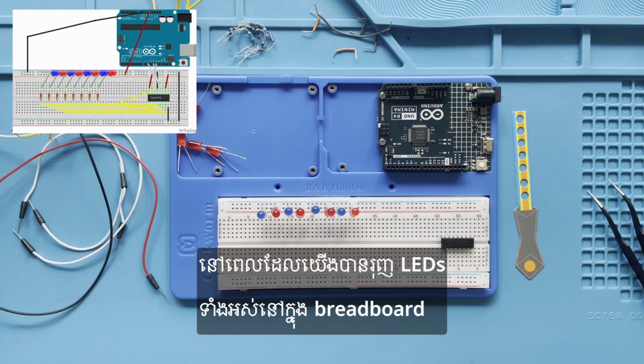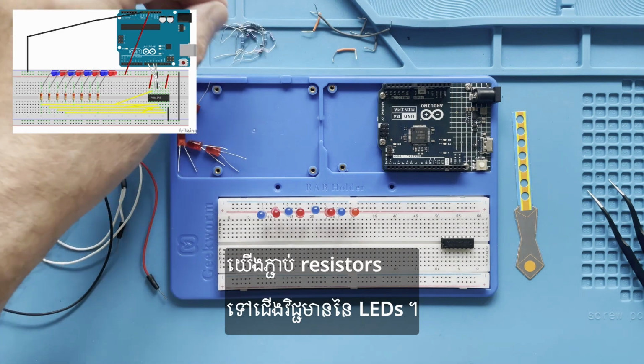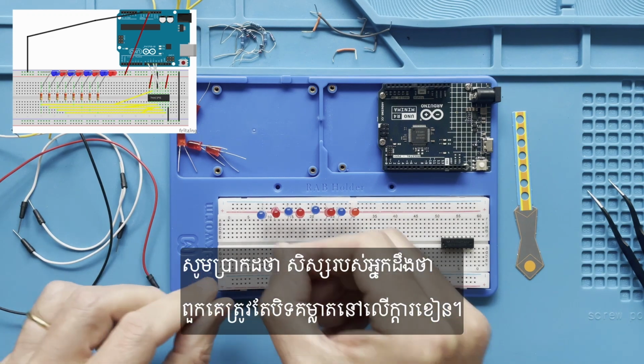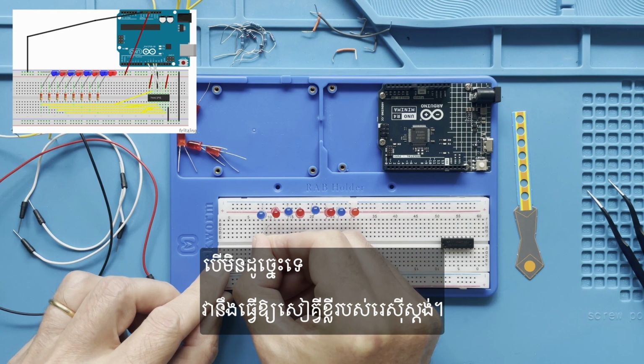Once we have pushed all the LEDs in the breadboard, we connect the resistors to the positive legs of the LEDs. Make sure that your students know that they have to bridge the gap on the breadboard, otherwise they simply short-circuit the resistor.